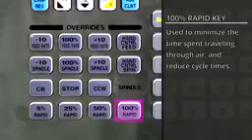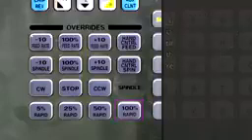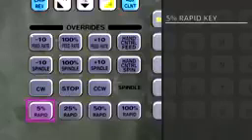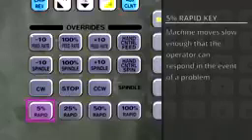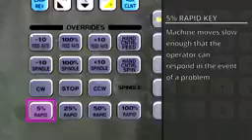In an educational setting, or when running a program for the very first time, it's advisable to set the machine to 5% rapids. When set to 5% rapids, the machine moves slow enough that the operator can respond in the event of a problem such as incorrect tool length offsets. There is little to be gained from running at high rapids on the first run of a part.